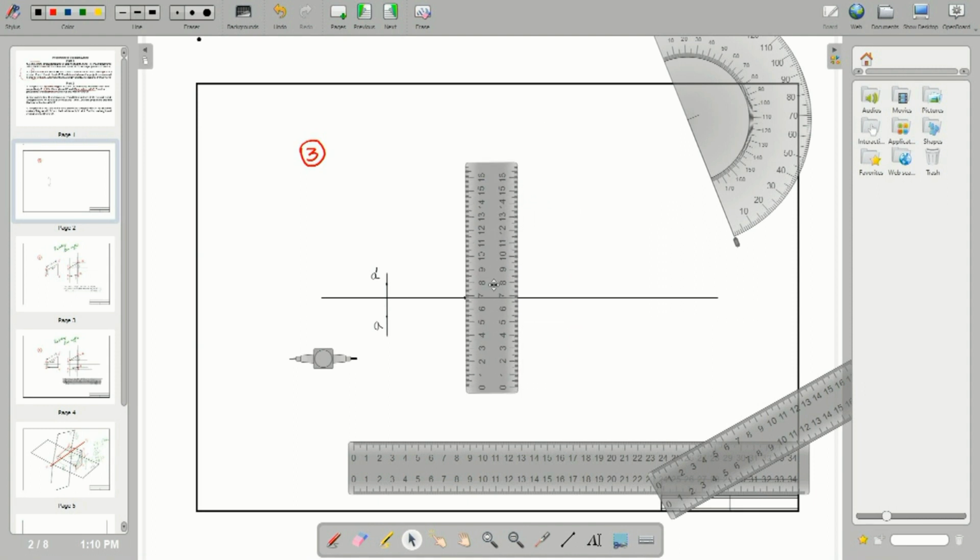So, why did I draw this? Because it is the plan view of the object that is 70 mm long. While looking from above, that should be below, is it? So, by marking 60 mm, above and below I have to draw a line, draw projectors, and also I draw for dimension. I have to mark dimensions.